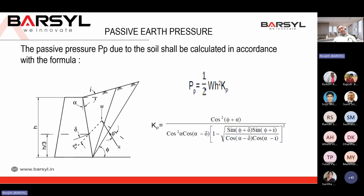Active means in the same equation K will be the active earth pressure coefficient, and for passive, the pressure is half into W into H square into Kp, where Kp is the passive pressure coefficient. The difference is that K is replaced by Kp. In usual cases we take the active pressure only. Passive pressure is actually a relieving effect, but railway does not always allow us to take the advantage of passive pressure. It will resist the active action. In some cases we will utilize this passive pressure also to make the calculations correct. So that is passive pressure.